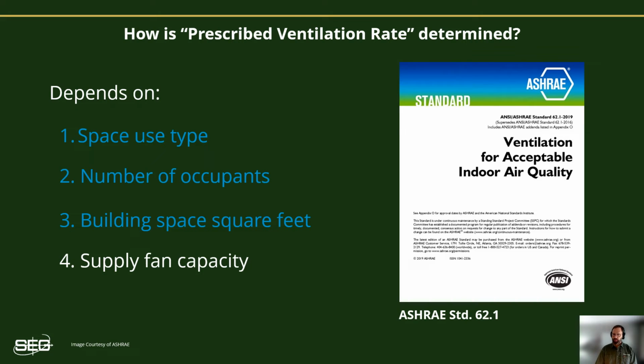So now that you're armed with this information, I encourage you to further your knowledge and become more familiar with the ASHRAE Standard 62.1. Also, you might try to acquire your building's occupied prescribed ventilation rate by going to the individual fan systems' installation and commissioning documentation.